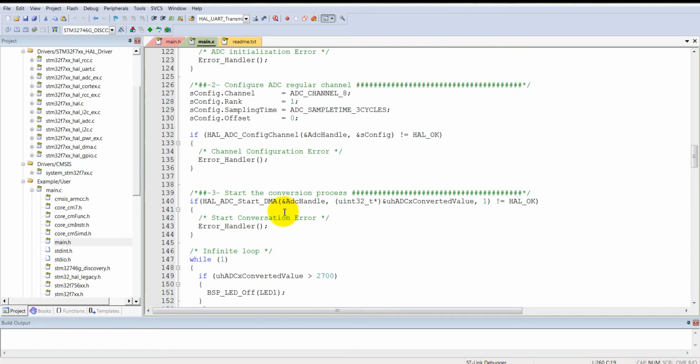As you know, the board doesn't support channel number 8 of ADC 3, so we cannot use ADC channel 8 on the board. Because of that, there are only 6 channels available on the board, channel 0 to channel 5. And unfortunately this is a read-only file, so we cannot modify it, obviously. So we cannot test this file on the board, but definitely we can test it in debug mode.